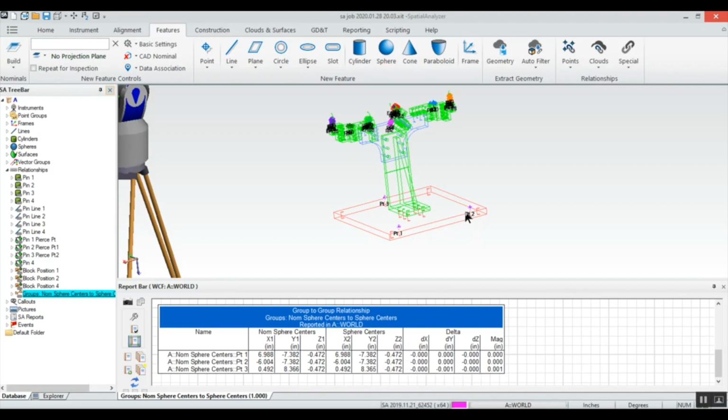So some of the things that we can do, you can actually store these points with the weighting turned off. We can also import points in with weighting. So you can take your nominal point set, give it the point name, its X coordinate, Y coordinate, Z coordinate, but then we can also set the weighting for X, the weighting for Y, and the weighting for Z. So you could simply import these in. If you had many points, you could do this over as well with weighting. So consider doing best fit with weighting to accomplish what they're doing with essentially what they're calling a 2-point alignment. Okay, hope that helps.